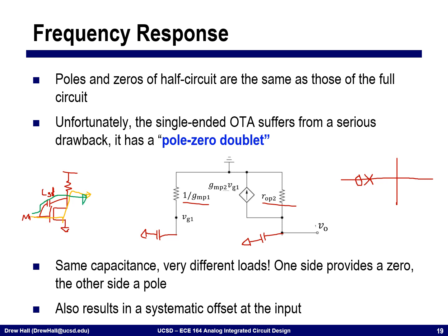The same is true in this circuit, except we're doing it by design. We have a current mirror up here that is copying the current from this side over to the other side. Okay? This is what's giving us the 0. The 0 is coming from this nature of copying the current and feeding it to the other side. So just in the same way that the single-ended amplifier had an alternative path to the output, this circuit has an alternative path to the output as well.